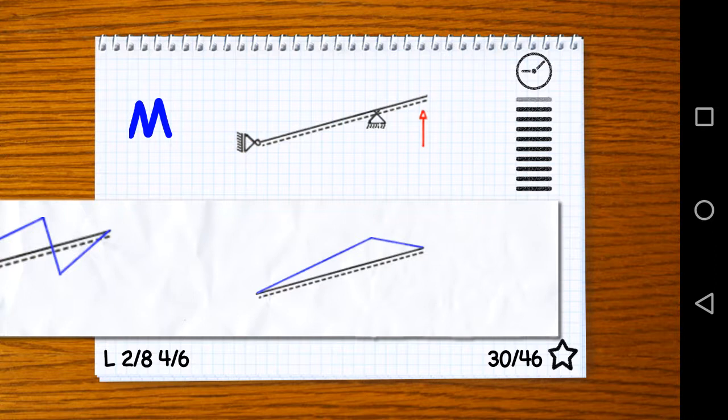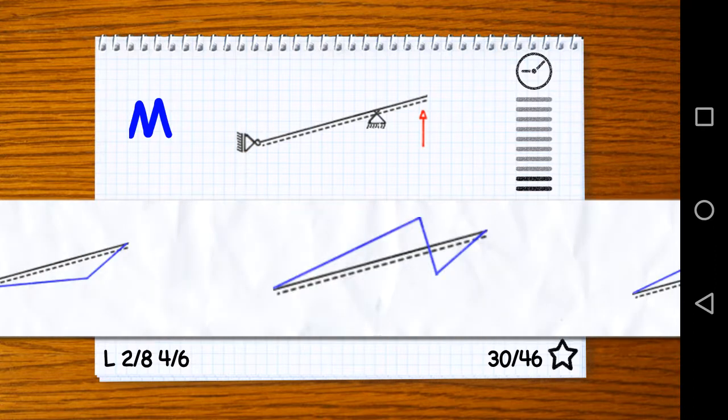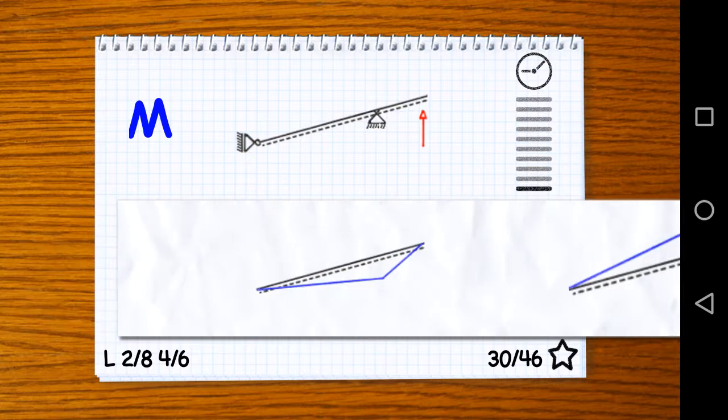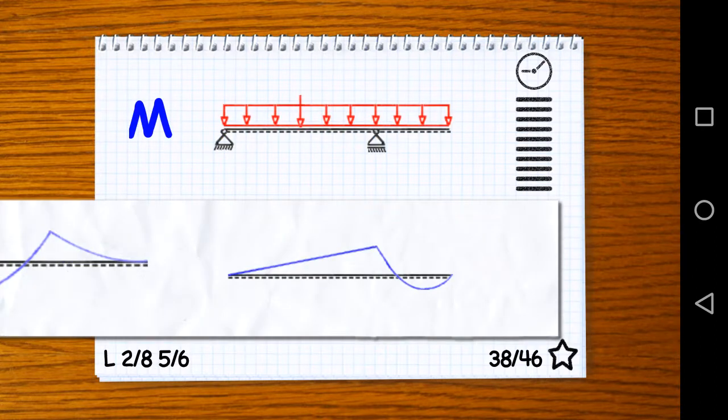Exactly the same system, but here we're interested in the bending moment. So now, basically just look at that cantilever looking part on the right side. What's going to happen because of that single upward directed load? That cantilever beam is going to bend upward, meaning that the tensile side is going to be below in this case. So the moment is going to be on the lower part, kind of positive side for us here. So this right answer is wrong. This one is wrong. We don't have any single moment to have a jump. So it will only be the left one.